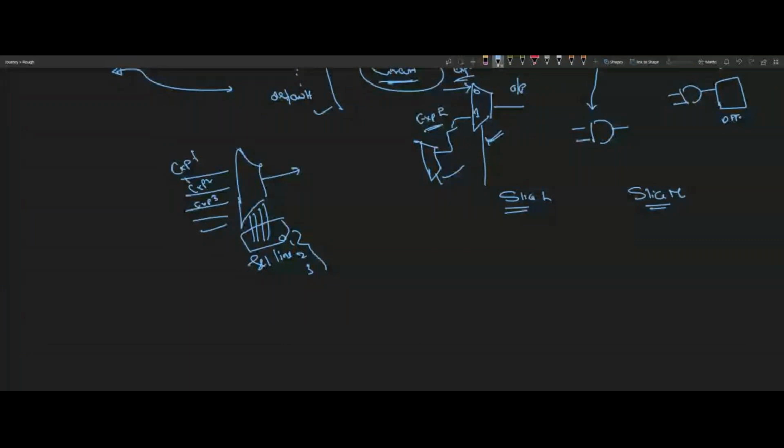One slice, how many bit shift register can it implement? One LUT can implement a 32-bit shift register. How many bits does one LUT actually store? A 5-input LUT can store 32 bits, and since it is a 6-input LUT, it can store 64. One slice can store 256 bits, but as a shift register it can use only 128 bits of that.